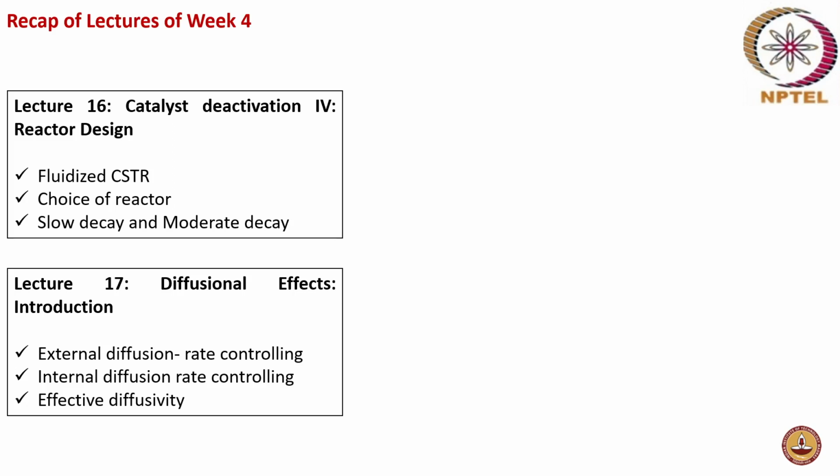Especially when you have decay of the catalyst, we have come across sintering, where the pores may get clogged, or there might be some agglomeration, right? So we cannot take the normal diffusivity as such.